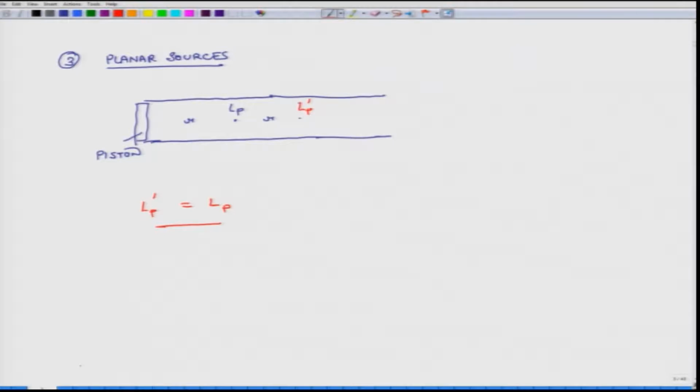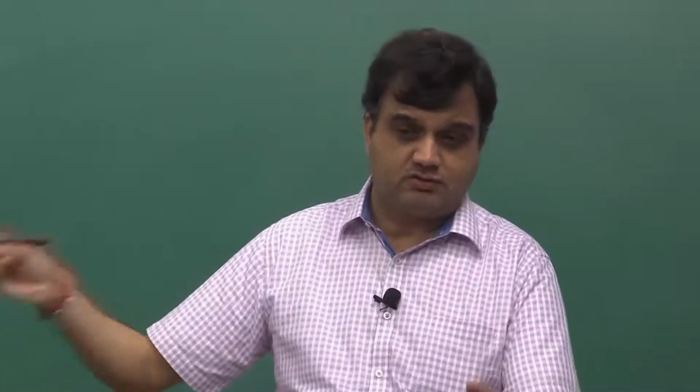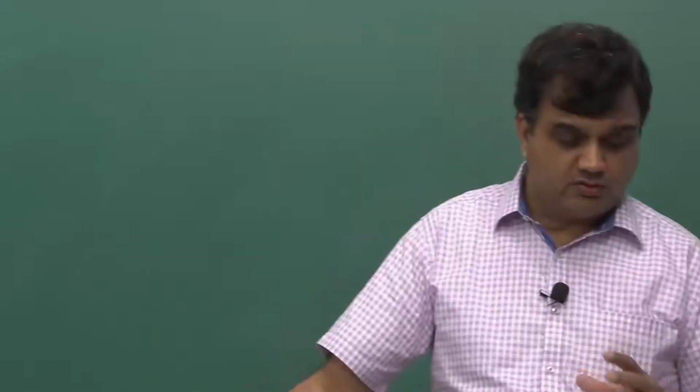Okay. So, what we have discussed are these three special sources of sound, and it is important to talk about those before we start talking about noise measurement and all that, because if you have in your situation one of these three types of sources, then each time you double the distance between the microphone and the source, either the sound pressure level will fall by 6 decibels or 3 decibels, or it may not fall at all. So, you may want to have this understanding before you start taking a lot of measurements, because then it may give you some idea whether your measurements make sense or not.